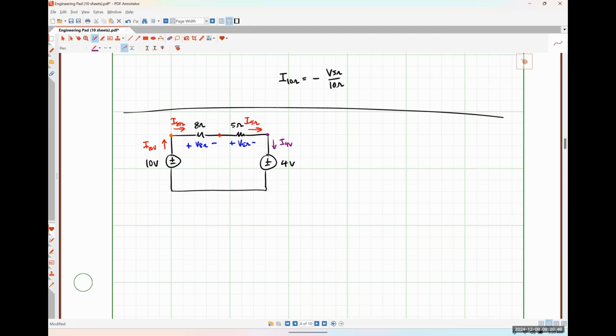So effectively, what I am trying to impress upon you guys right here is that whenever we have elements connected in series like this, they all have to share the exact same amount of current because there's no place for the current to branch off or change, right? So at every single node, I in equals I out.